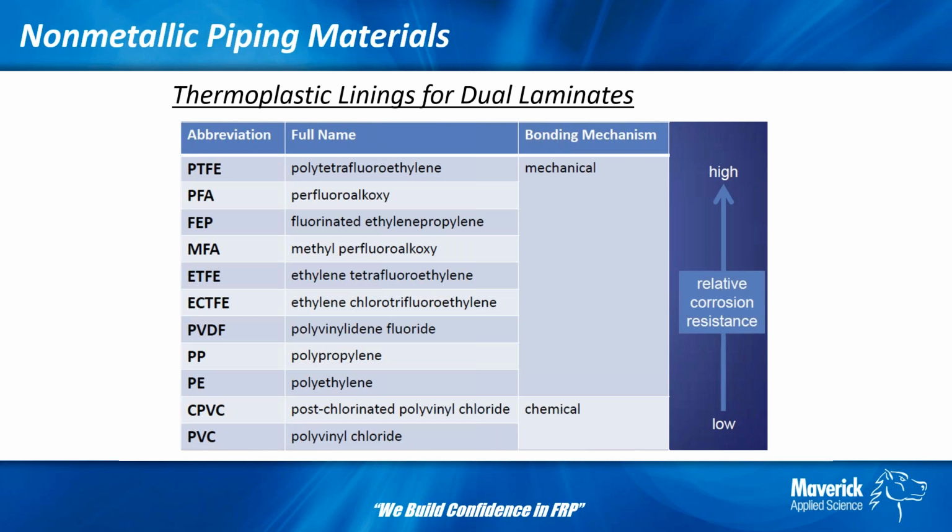No. I guess to put it simply, it needs to be a controlled environment. It needs to be a closed environment. So if it's a pipe or a vessel, it should be in an enclosed oven. You want to have walls, ideally insulated. It needs to have thermocouples, ideally inside the pipe, on both ends of the pipe, where you're measuring temperature every minute, every 30 seconds, every 10 minutes, something like that, doing regular checks, and it's not a hand process.